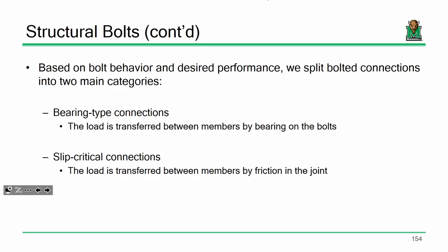Yes. Just that the magnitude isn't enough to be considered. Exactly. To elaborate on that a little bit, when you have a bearing type connection, essentially all you're worried about is getting the bolts just snug tight. And snug tight is a very loose definition, okay?